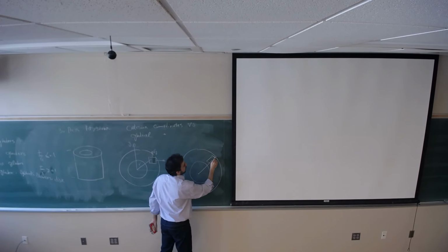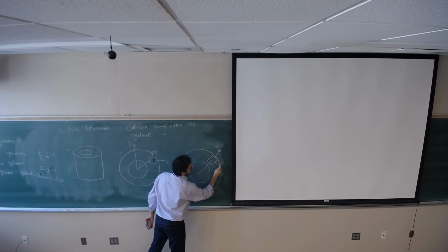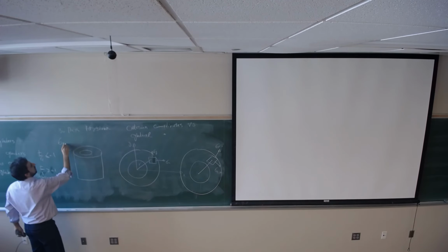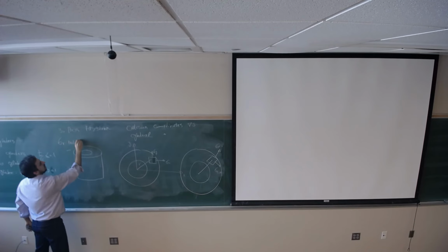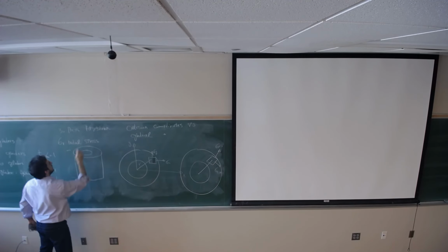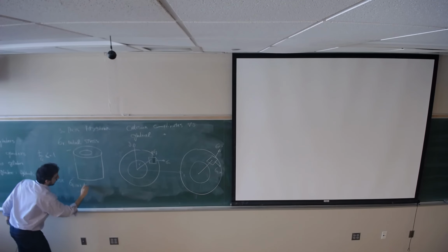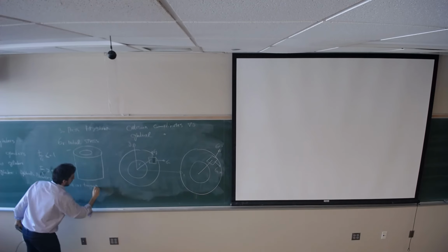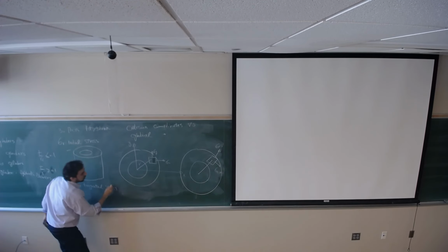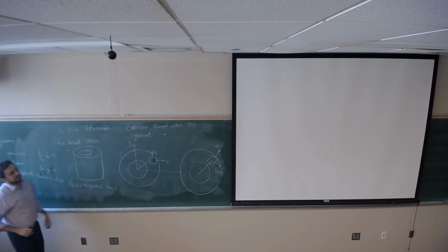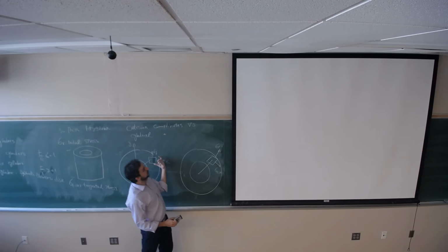Sigma x and sigma y are going to change to sigma r, or radial, and tangential, sigma t or sigma theta. So for cylinders, we are dealing with sigma r and sigma theta rather than sigma x and y that we used to have in our analysis, because we just changed the coordinates from Cartesian to cylindrical.